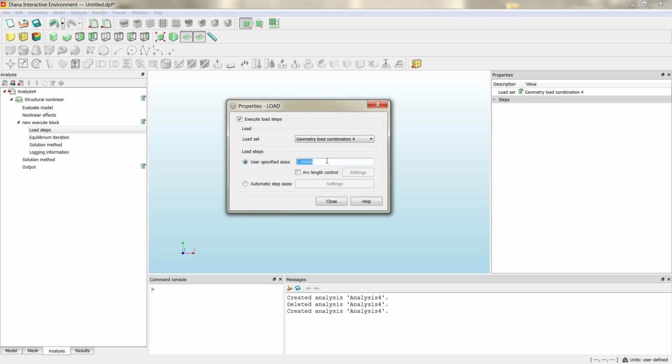So we can apply the defined load one time, or we can apply it 10,000 or 100 times. It doesn't matter, it's up to us. So we can just define a load with a value of 1 Newton per meter, and then we can apply 8,000 times this load in one step. That means we are applying 8,000 newtons per meter.